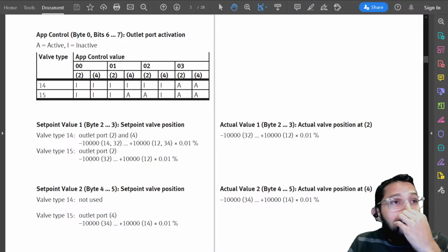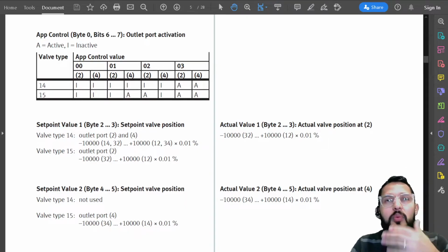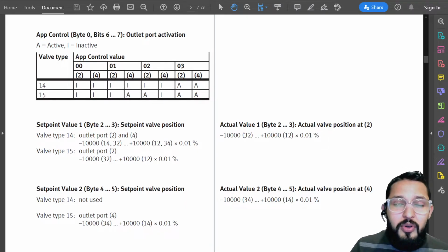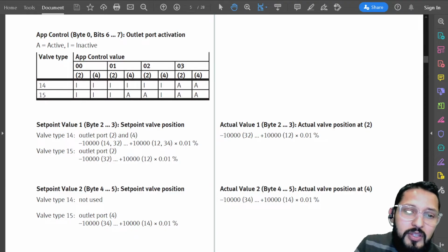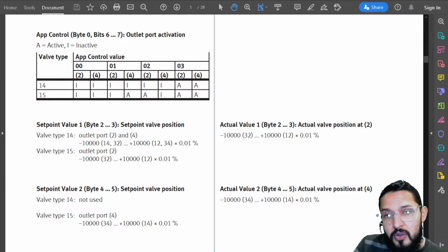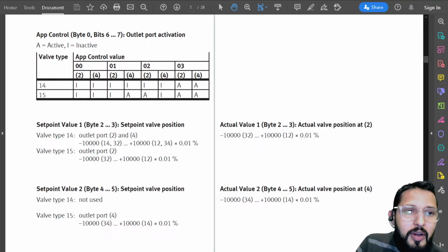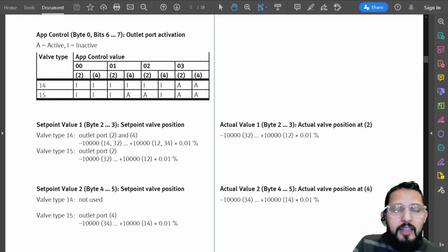Now, because I know that I need to set the set point value to something, what I did here, just to visualize how this will look like with, for example, a sine wave or a sinusoidal signal, I'm using this sin generator. This is included in a library from OSCAT. This is a company in Germany, I believe, that created an extensive library actually. They have good things here, and inside of this library, they have these signal generators. So I grab this gen sin, and this allows me to generate a sinusoidal signal, right?